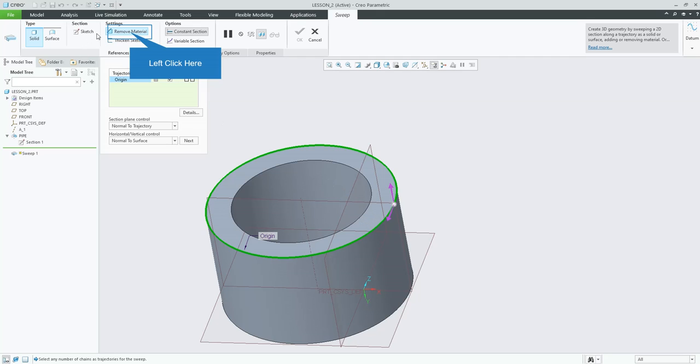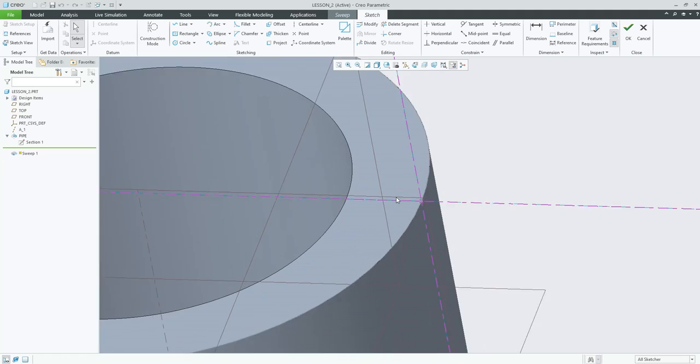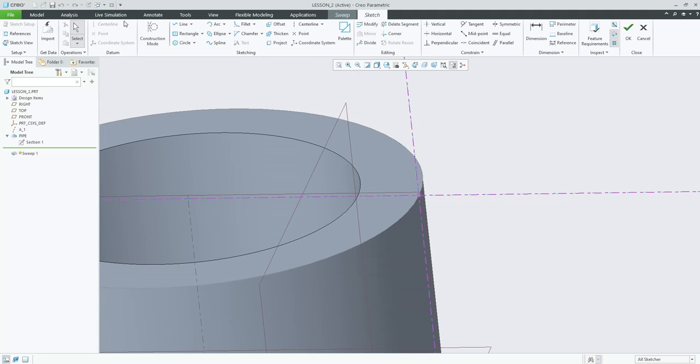So now you want to go to, let's do a remove material. So that's an option, and just like the extrude, Revolve has the same option. You can do a revolved remove material. Same option. Same with the sketch. Do a select here, or go to our sketch here, and let's just sketch kind of a weird shape.